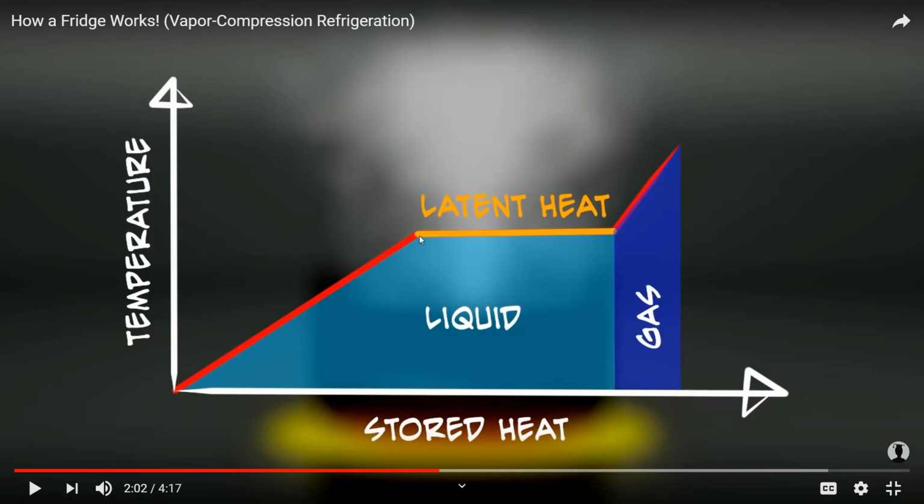The first thing is that in this area we have saturated mixture, saturated liquid, saturated vapor, but not the liquid. Liquid is in this area. And then the second mistake is this part. We have vapor here, but not gas. We already discussed the difference between gas and vapor.